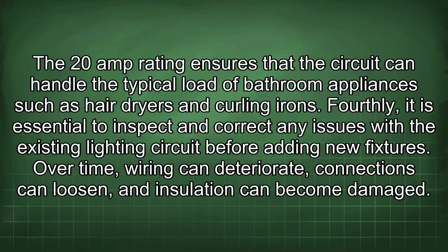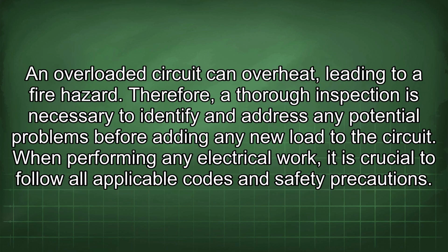Fourthly, it is essential to inspect and correct any issues with the existing lighting circuit before adding new fixtures. Over time, wiring can deteriorate, connections can loosen, and insulation can become damaged. An overloaded circuit can overheat, leading to a fire hazard. Therefore, a thorough inspection is necessary to identify and address any potential problems before adding any new load to the circuit. When performing any electrical work, it is crucial to follow all applicable codes and safety precautions.